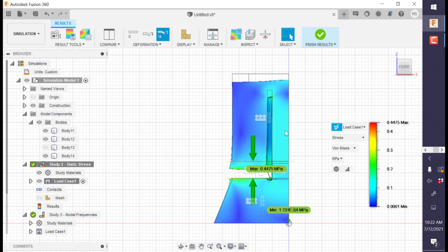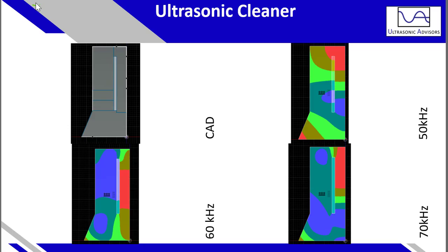If you did an experiment where you had a very thick center bolt, the piezo would be more constrained, so your capacitance would decrease further. This is a way of understanding and investigating these results. So here are those results again. Here's the CAD model.